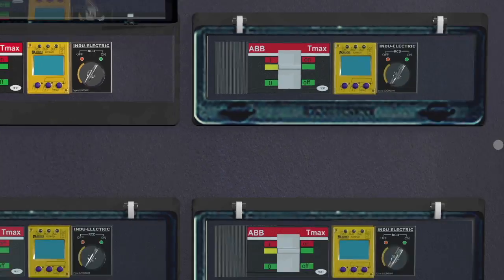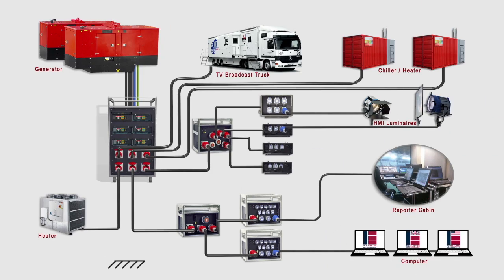So, what are the ideal settings for the RCMs? To help us answer this question, we first want to explain a couple of terms: leakage current and fault current. What exactly is leakage current? Leakage current in this context is an electric current that leaks out of the intended circuit into some other path under normal operating conditions. This leakage is of course undesirable.